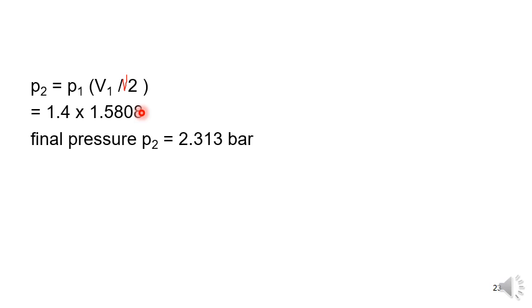We don't know the R value. So how will we get the R value? R is equal to Ru by M. The universal gas constant Ru is the same for all gases, so you have to remember that value also. Ru is equal to 8.314, and the molecular weight of CO2 is 12 plus O2 16, O2 means 32, 32 plus 12 is 44. By using the formula R is equal to Ru by M, we get the R value.